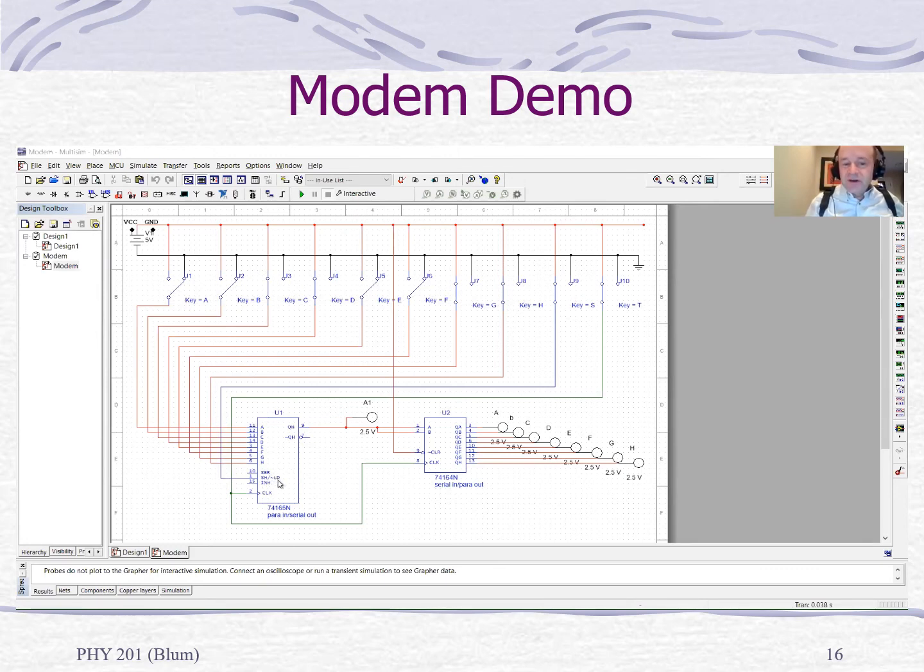The little tilde in front of LD means it's loading when that input is low. And the T is a clock, and so we must go through a clock's edge each time to get an action. And then these two shift registers are sharing a clock. They're synchronized. And so as the data comes across this transmission line from QH into A and B, then that data is going to be read into the receiver shift register in serial, and then we will have the data that we fed in out.